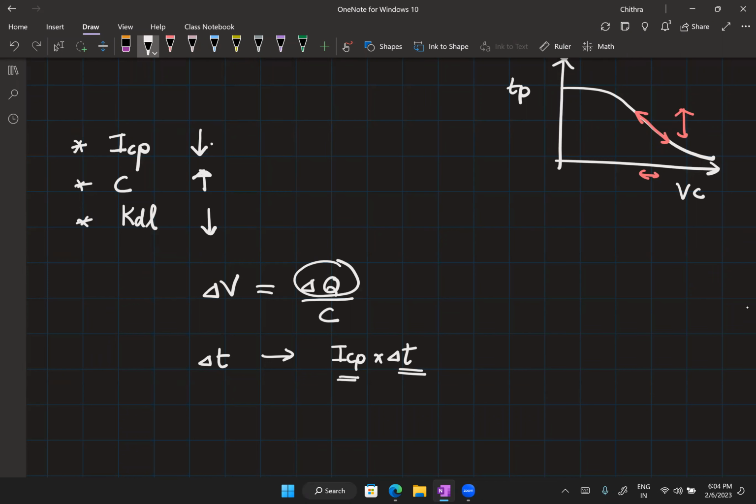Now, the other problem is what you mentioned. All of these changes that we have made are going to increase the locking time. It is going to take more time for us to reach the final lock point. So I'm slowly bringing you into this concept of tracking bandwidth. You can also think of it as small signal bandwidth. If I have some smaller variations in your circuit, how should I adjust these parameters such that I can track it faster or I can track it slower, right?